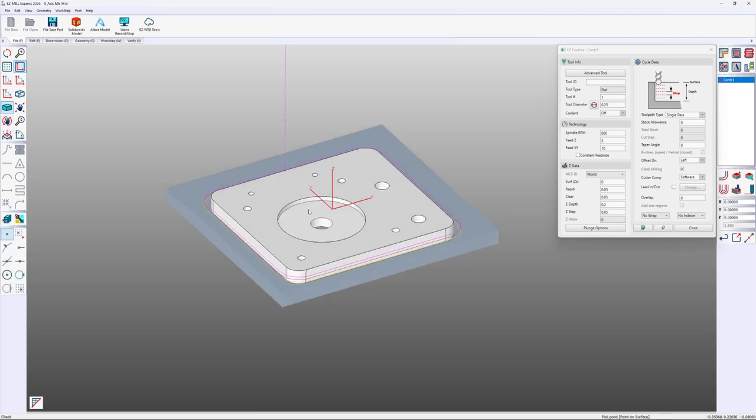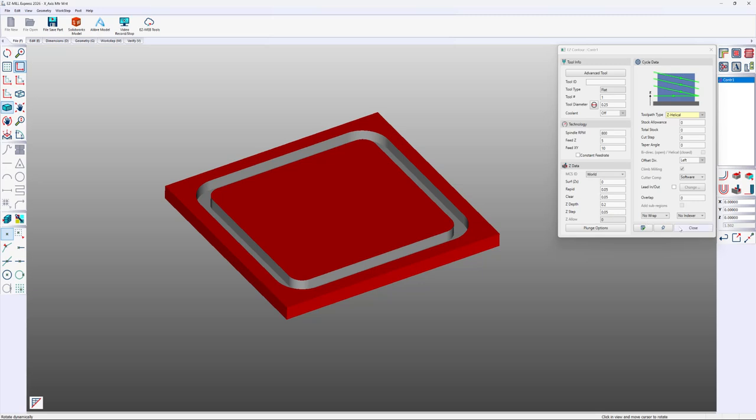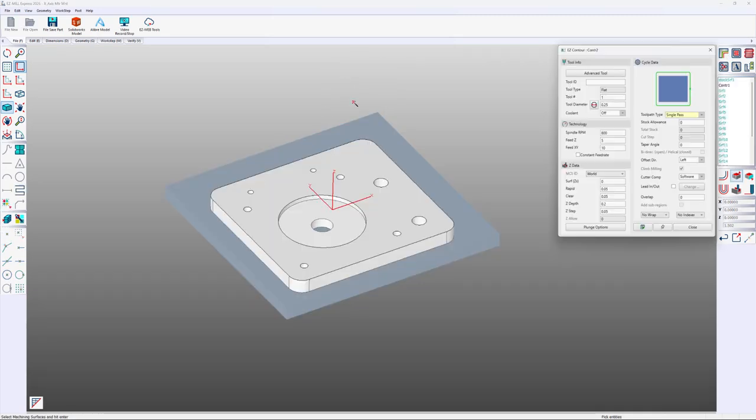Maybe a practical strategy would be to do a helix around the part. We'll just change that to Z helical. As you can see in the graphics, it works like a corkscrew. There's our start point up here, and it comes around and spirals to depth. Now to create the tabs, now let's go with 0.3 for depth. We don't need a step.